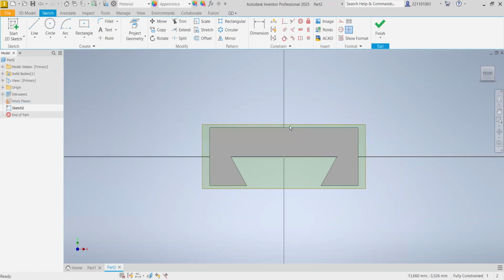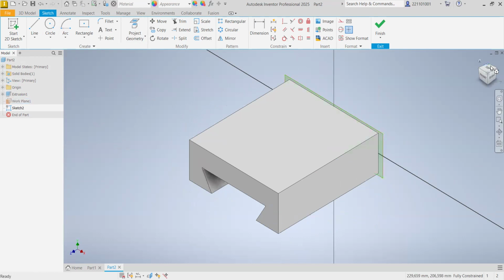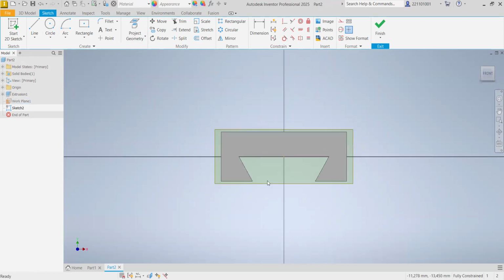As you all know, even if I can draw a line, I'm not drawing it here. I'm drawing it on that side because the plane is on that side. How to cut it? You have to go to your laptop and press FN F7. That's how you cut it. But the reason why you can't see this one is because the plane is at the back. So if I'm cutting what is behind or in front of the plane, it's the whole object. That's why it just disappears. And if you want to bring it back, it's also FN F7. So let's just keep it so that we can use it as a reference.